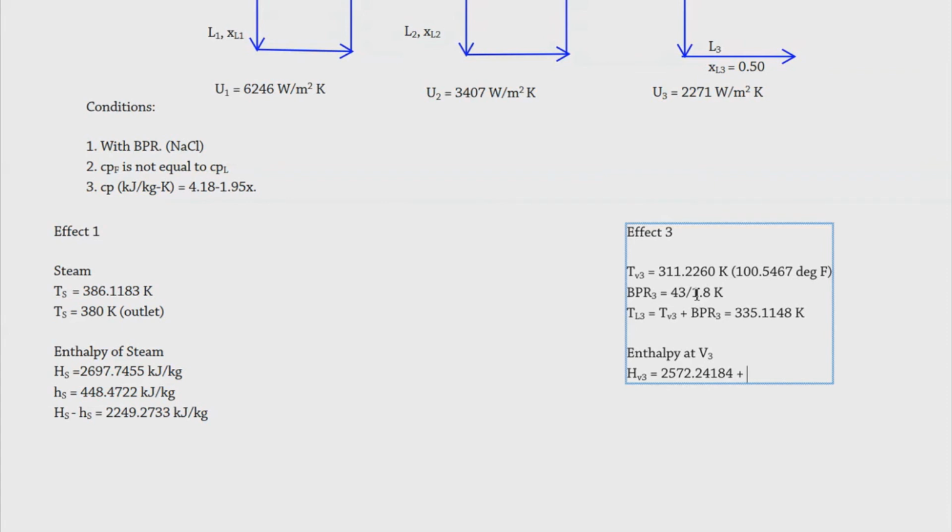So, yun. And then, i-add natin ngayon kasi diba nagkaroon na tayo ng boiling point rise. So, technically, naging medyo nag-above siya dun sa kanyang saturation. Medyo naging superheated yung ating vapor. So, yung kanyang outlet magiging merong counting sensible heat, so that's 1.884. Yun nga pala sa English, sa SI, yung 0.46 natin before maging 1.884.